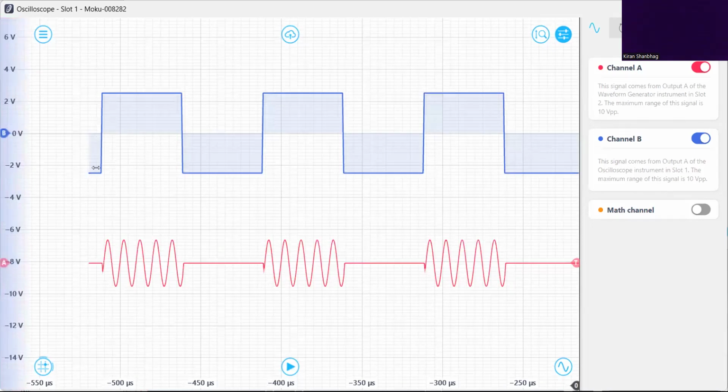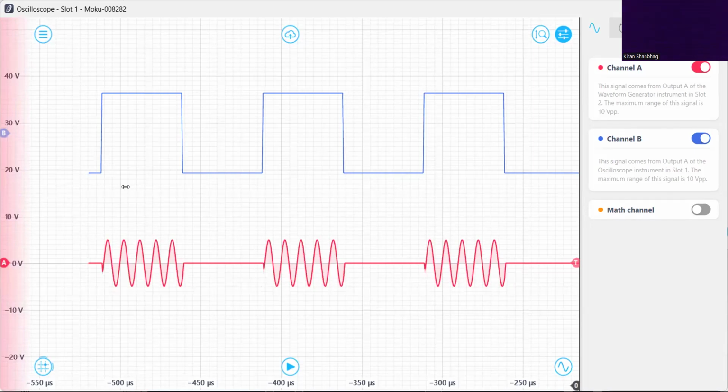This is not an output actually. You can see this is the waveform that we have generated from the oscilloscope. And then this is our modulated output. So what happened here was we used AM, amplitude modulation. Whenever this was zero, the connection got cut off and there is no wave. So there is wave, no wave, wave, no wave. That is our ASK.